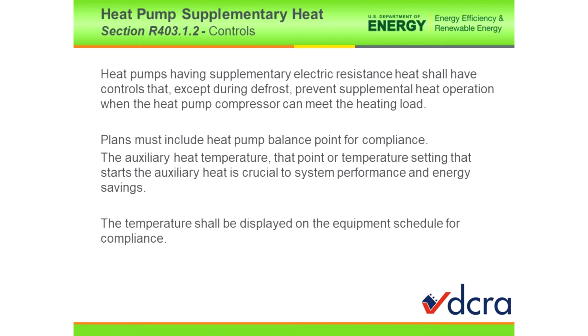Now, if you are installing a furnace, then you say it's a furnace, because you have a furnace that sits on top of a blower motor which has a fan. The designation for that type of system is a furnace, and then you have an air conditioner on the outside. If you have a heat pump with a furnace, then you just tell us: furnace, heat pump, auxiliary heat is provided by the furnace. Then we're good. But if you say you've got an air handler, and then you show us that you've got a furnace, then it just confuses us, man.